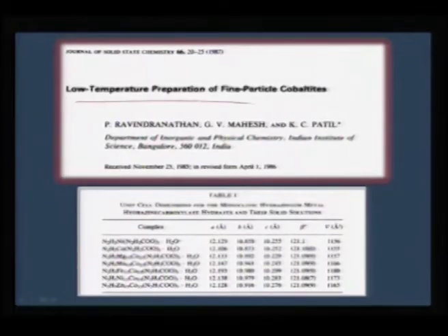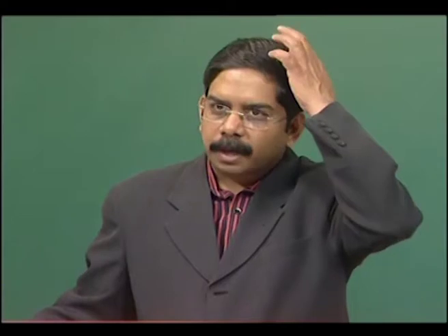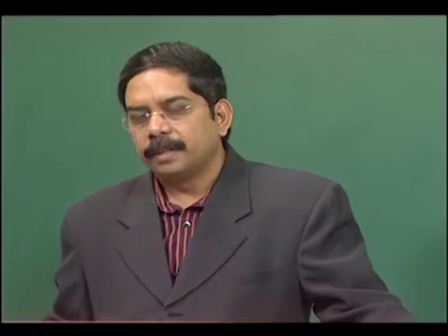So, if we can understand the notion of a solid solution precursor, then we can look for many applications for functional materials. This is one of the finest papers that has been published in 1987 by Patil's group from IISc Bangalore. What they attempted was using hydrazine precursors to get corresponding metal oxides. Why are hydrazine precursors useful? As you would have seen in the previous lectures, when I talked about combustion, we talked about the potentiality of hydrazine precursors because they release enormous energy during decomposition.